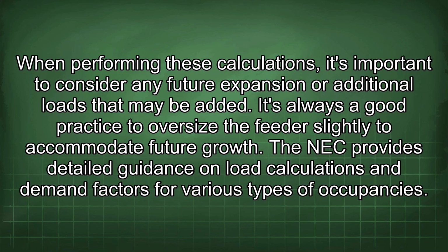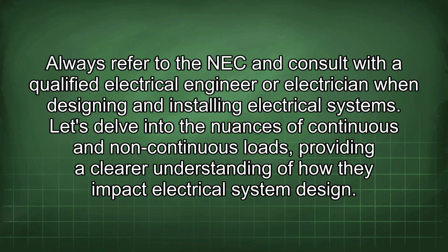When performing these calculations, it's important to consider any future expansion or additional loads that may be added. It's always a good practice to oversize the feeder slightly to accommodate future growth. The NEC provides detailed guidance on load calculations and demand factors for various types of occupancies. Always refer to the NEC and consult with a qualified electrical engineer or electrician when designing and installing electrical systems.